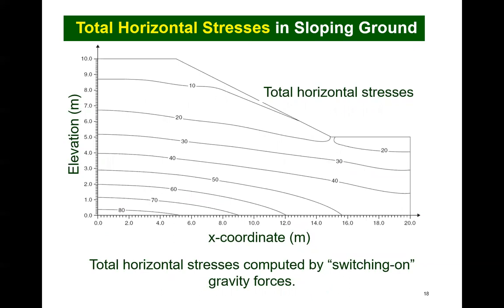Under sloping ground conditions, the total horizontal stresses can only be calculated based on an understanding of the soil properties such as Young's modulus of elasticity and Poisson's ratio. The calculation of total stress fields is often made more difficult because sloping surfaces are usually the result of a series of soil excavations or the placement of fill.